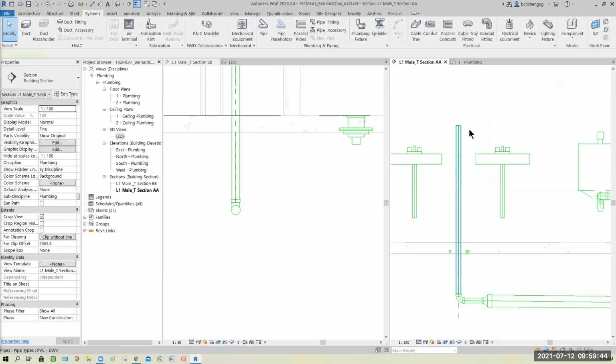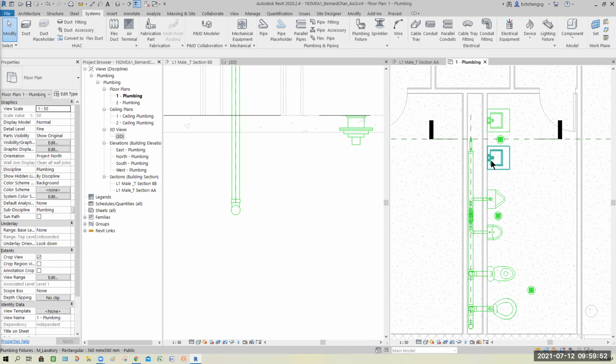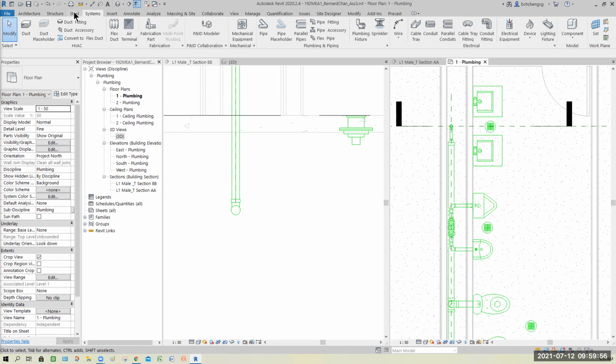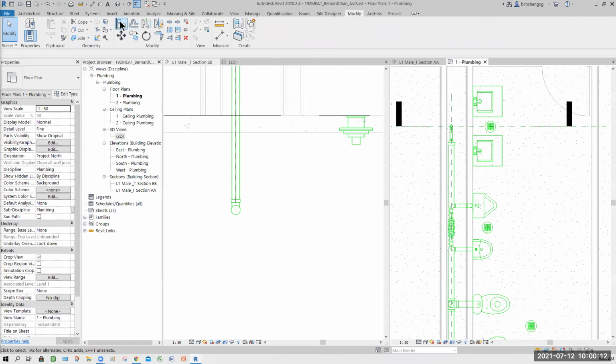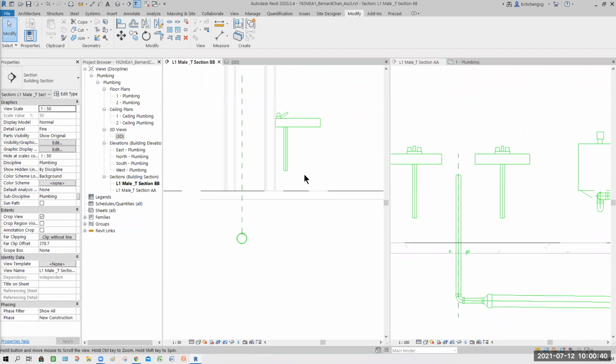Okay. So this is good. Lower a bit. Yeah. Then now I change back to one of it. Okay. So align. Am I too fast? Okay, right. Yes, sir. Okay. So I'll go to modify, align, set the center, align my section line. But I can see sometimes quite difficult to adjust. So must use what? Tab key. Tab is to toggle your selection. Remember. So once you set it correctly, then things will be easier. See, now connection is back.